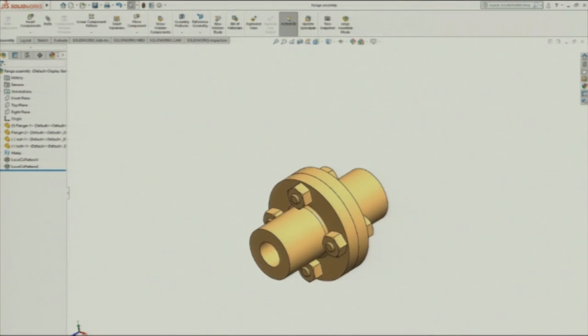For the appearance, for instance, there are certain complex components, different assemblies where we need to see the components. So, this coloring pattern can be used when we have a big assembly and different parts meeting, we can show the components or parts with different colors. For instance, if there are different sizes of bolts, we can show all the bolts of 5 mm with green color, all the bolts of 10 mm with a light green color, and the components made of different materials, like gray color for steel, then a little brownish color for copper.